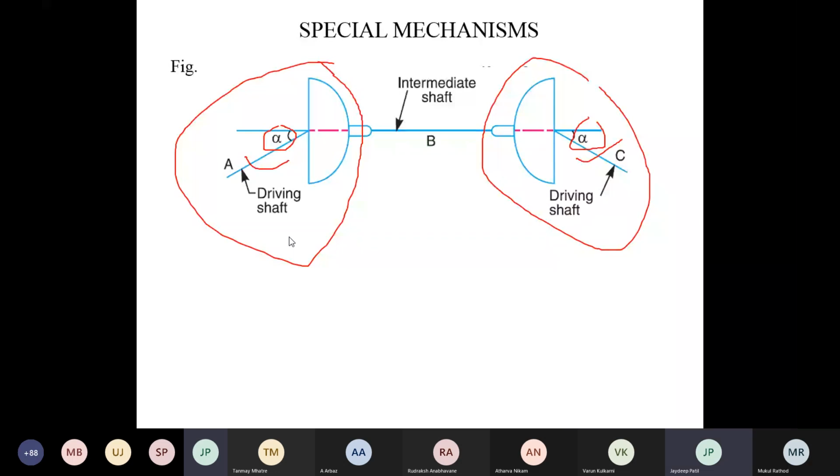Okay, now here we end this module number 2. In module number 2 there are different points, and it is a theoretical module. The first one is a pantograph, then straight line generating mechanism. In that, the exact straight line generating mechanism is your Peaucellier mechanism, and Hart mechanism is your approximate straight line generating mechanism. उसमें कौन सा था? Grasshopper mechanism, Robert mechanism, and Tchebicheff mechanism.